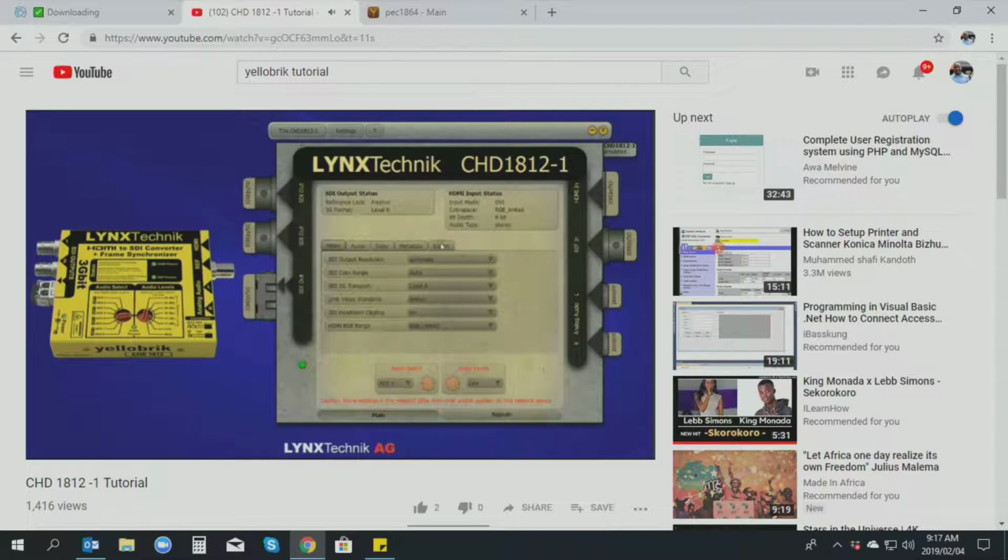We work our way across the tabs at the top here to see what we can do. Obviously they're the video adjustments. Now we go to audio adjustments, and again we can set the bit depth 20 or 24 bit, audio channels 1:1 or convert. Again, that's a little bit involved, this conversion. So you go, what's this? What does that mean? And it means that they're remapping the audio channels per some SMPTE standard. Alright, so that tells you precisely what it's doing. Keep that on 1:1. And then embed the audio, 3G level B audio into what stream? Stream A and stream B, or stream A only, stream B only. Again, that's if you're in 3G level B mode. That would be an important adjustment.